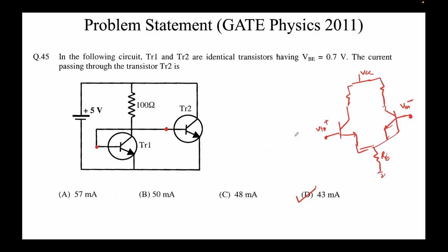So it cannot be converted. It uses two BJTs, yes, and the power supply to their collectors is the same, just like over here it's plus 5 volts. The emitters are shorted just like here, but the base voltages are different. Here the bases are also shorted in a current mirror, while for an operational amplifier, or let's say in a differential amplifier topology, the input signals are different.